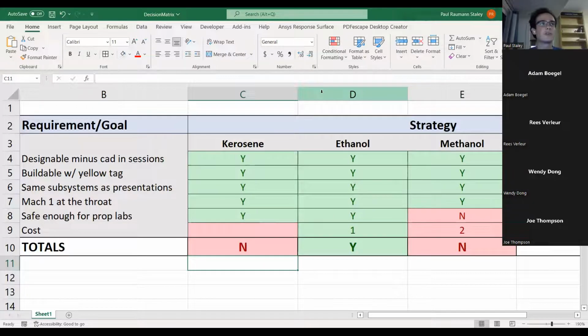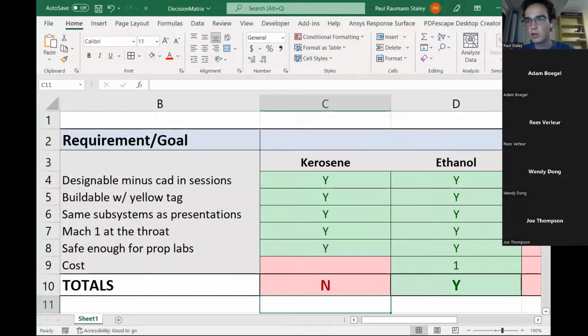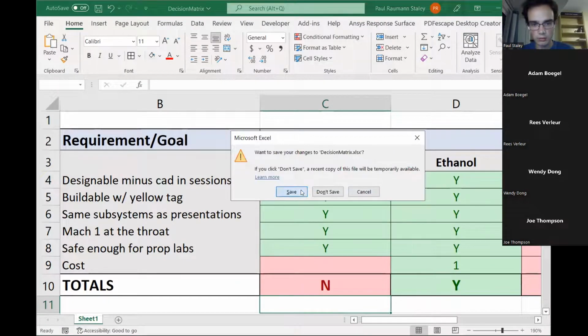We could think about m dot and density forever, but that's not really in the goals for this engine. It only needs to hit Mach 1 at the throat. It doesn't need to have any crazy performance. And effectively, Mach 1 at the throat is the bare minimum for is there fire happening. These all pass that. And I think it would be relatively easy for you to figure that out on your own by looking these up in books and things. But if those are resources you're not aware of and are interested in, I'd love to help you find them. All right, save.